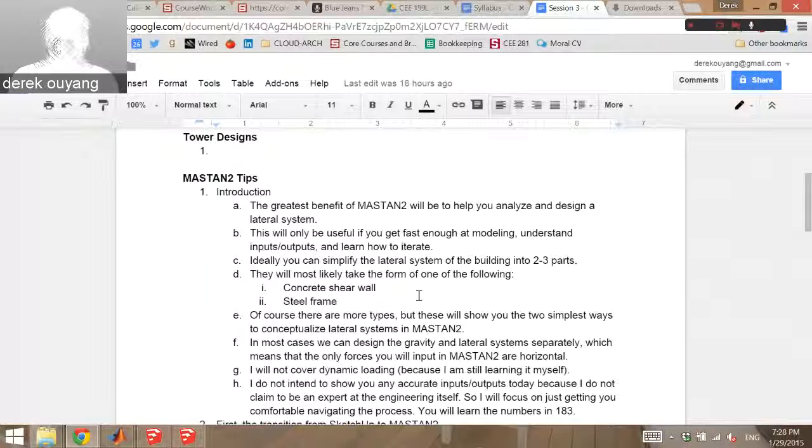And then you're just going to apply those wind loads to one or two specific parts of your building that are not even going to worry about gravity loads and are just going to hit those lateral loads. And it's going to pretty much take it on for the whole building. So one example of this would be a big moment frame, either on the edge of your building on all four sides or somewhere in the middle. But wherever it is in the building, all those wind loads on whichever side of the wall it's hitting are going to somehow eventually get to that lateral system. And it's going to hit it basically at every floor.